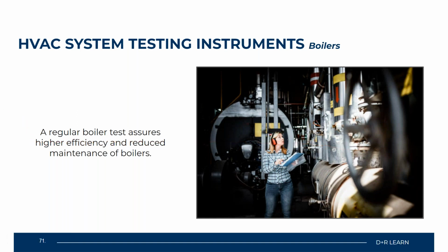So some of the things you're going to be testing for in your boilers are CO2 leaks or any type of CO2 detection, your boiler water quality and the chemical treatment of that water loop, and any leaks that may be happening on your supply and return heating water lines. You're also going to test for proper combustion in the combustion chamber of the boiler system.